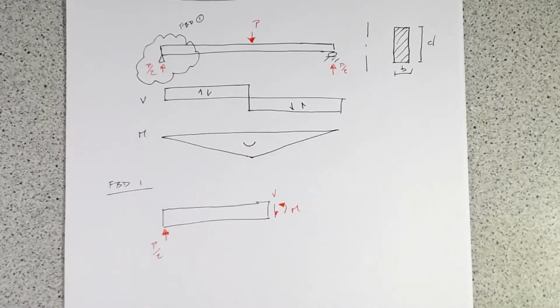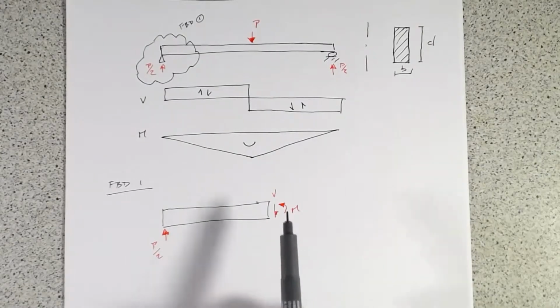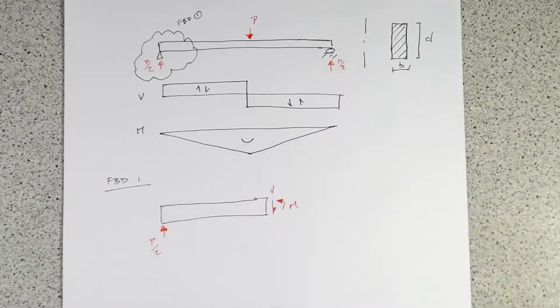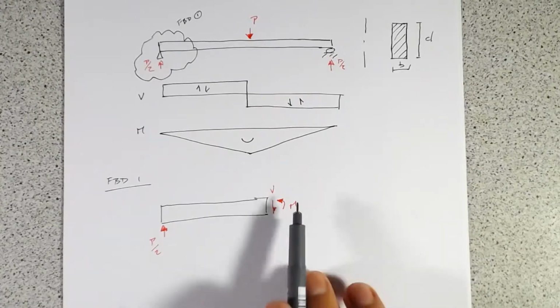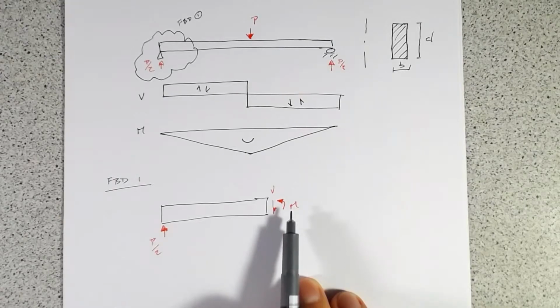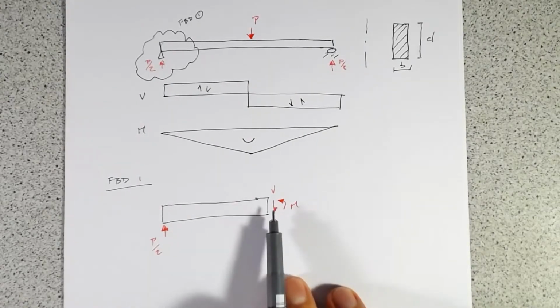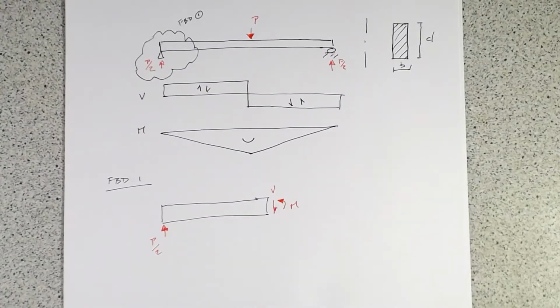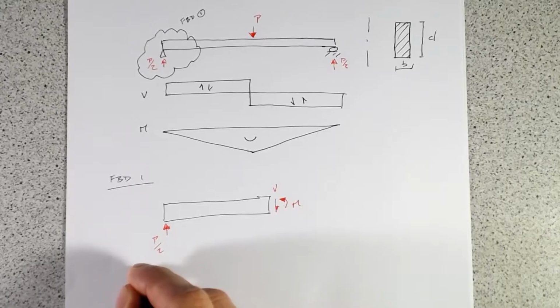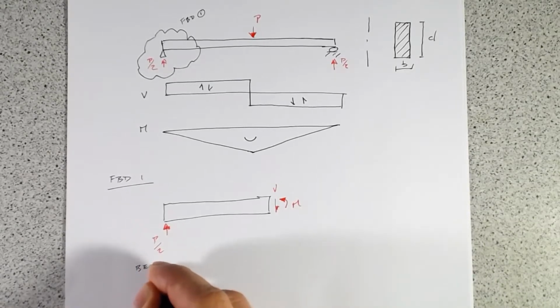All right. But if we're interested in shear stress, really what we want to know is how this force acts over this area of cross-section, because that's all our stress is, a force acting over an area. Well, we can think about that by breaking this out into the two different forces. We can look at first our bending, which we've learned what that distribution looks like. And then we can use that to help understand what our shear force distribution is going to look like. So if we just look at the bending component,